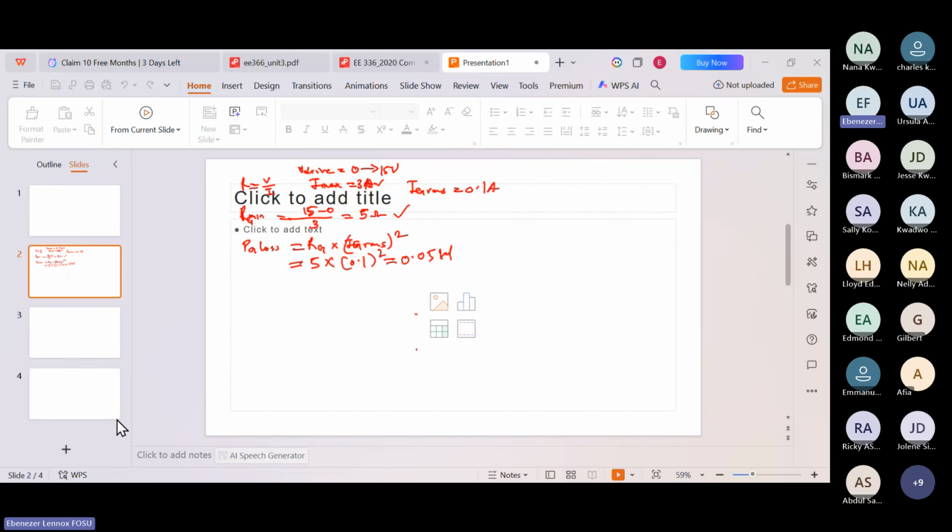So we'll have 5 equal to 15 into 1 minus e exponent minus t over the time constant. So let me still keep it RC so that when we make t the subject, we'll come and substitute it, right? So this one you can expand and simplify. So you're going to get 5 equal to 15 minus 15 e exponent minus t over RC.